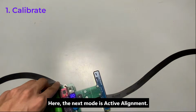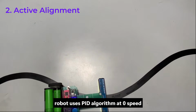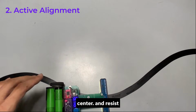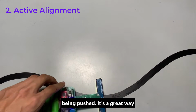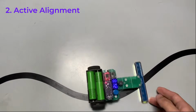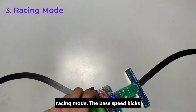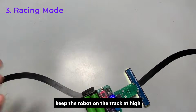Next, the mode is active alignment. Before the race, the robot uses the PID algorithm at 0 speed to actively lock its sensor perfectly onto the line. It's a great way to test the PID stiffness here. It looks cool. And the final mode is the actual racing mode. The base speed kicks in and the PID algorithm takes over to keep the robot on the track at high speed.